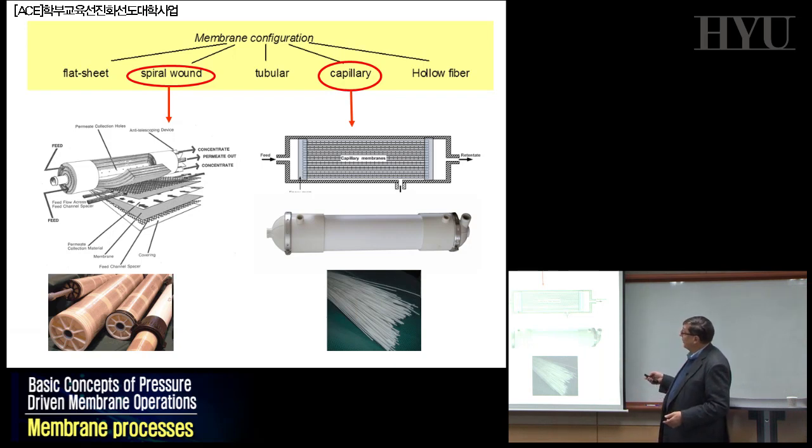Keep in mind that when you have a spiral, the same flat sheet, if you combine a spiral module, one time they were 4-inch, 8-inch, now they are becoming, here in Korea, you are producing huge modules, 36-inch, 27, etc. That means in a spiral wound module of 4-inch, something with this diameter, 80 centimeters, there are about 7 square meters of membranes. Now you can make modules where instead of 7 square meters, you can have 300 square meters. You can have 500 square meters in a single module. That means the system is becoming more and more compact, you save a lot of material, etc.